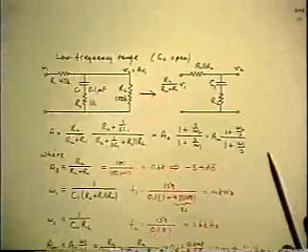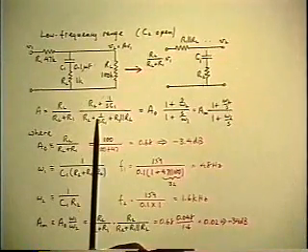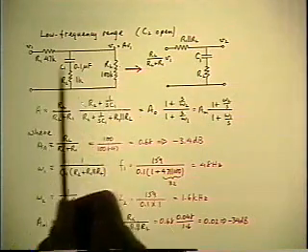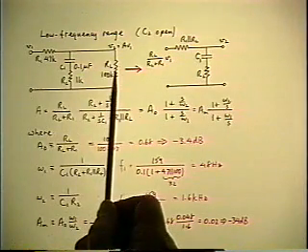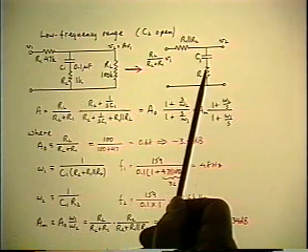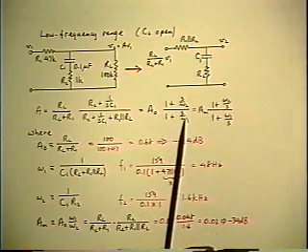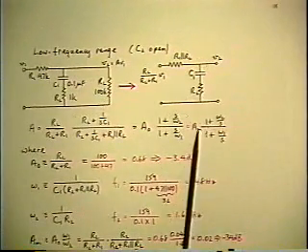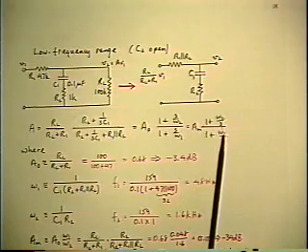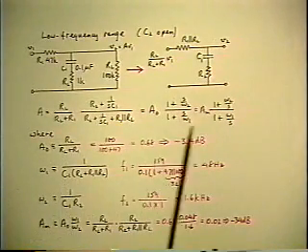So the solution finally can be written by solving the two pieces separately. This part of it is the same lag lead network we talked about before after you make the Thevenin reduction. So you get a zero frequency flat gain and a normal pole and zero, or you get a high frequency flat gain and an inverted pole and zero, and you can write these results down directly.